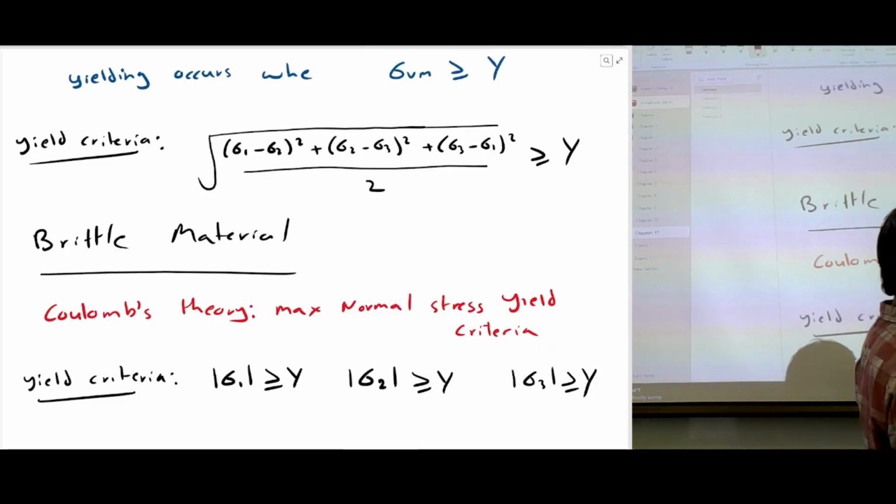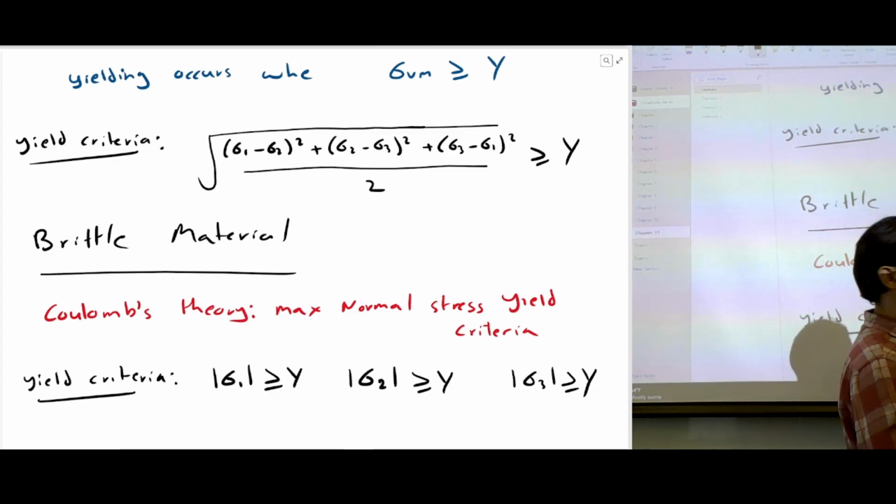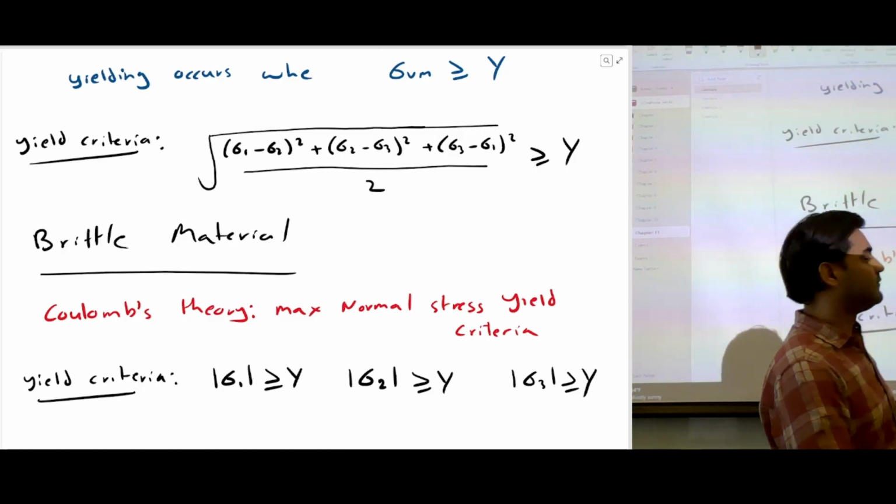So we can calculate stress 1, stress 2, and if you have a three-dimensional stress element, stress 3, from the stress element, and we have to compare it with the yielding of material under uniaxial testing, and if the stress is higher than the yield, then we will observe yielding.